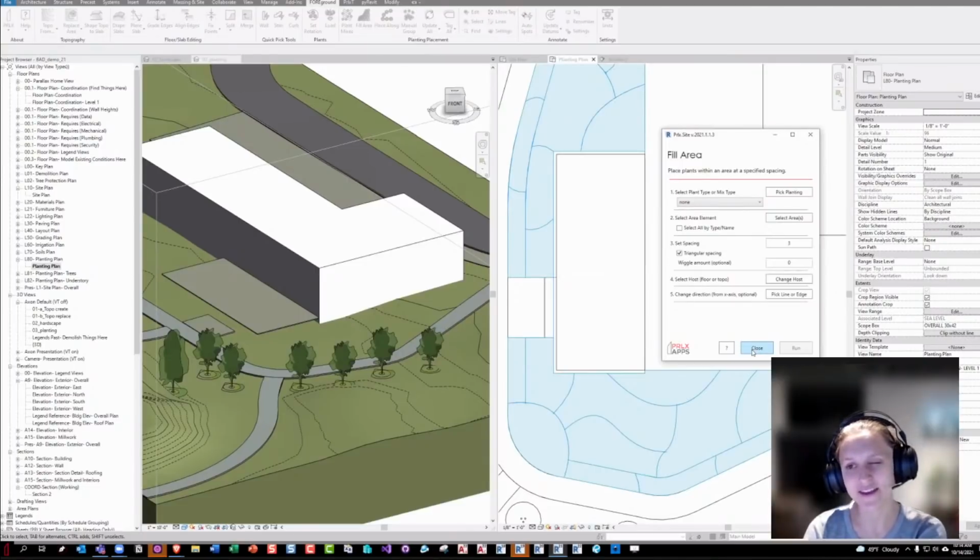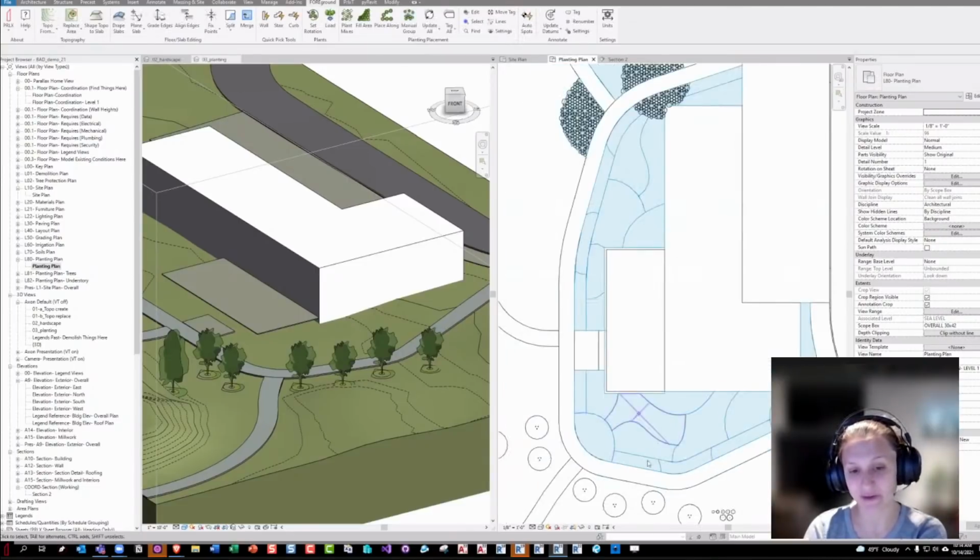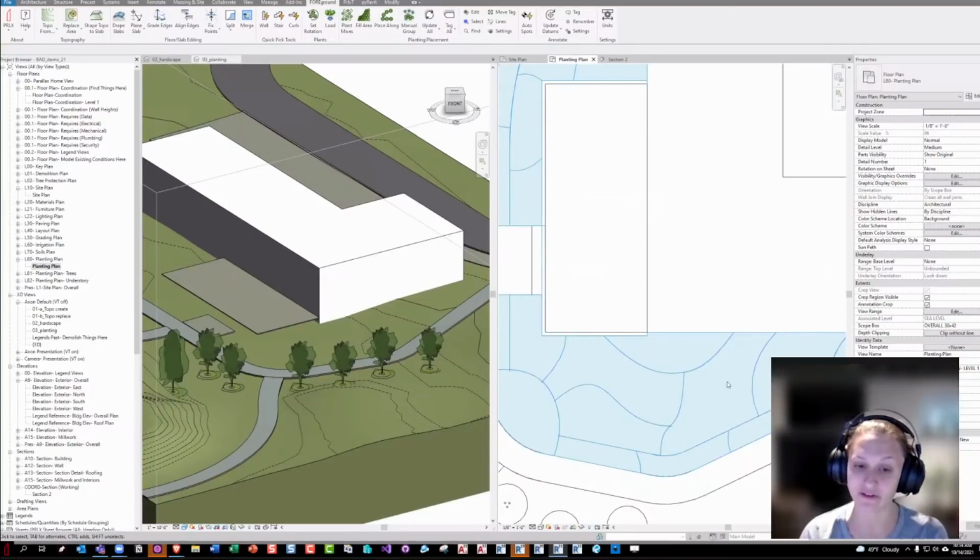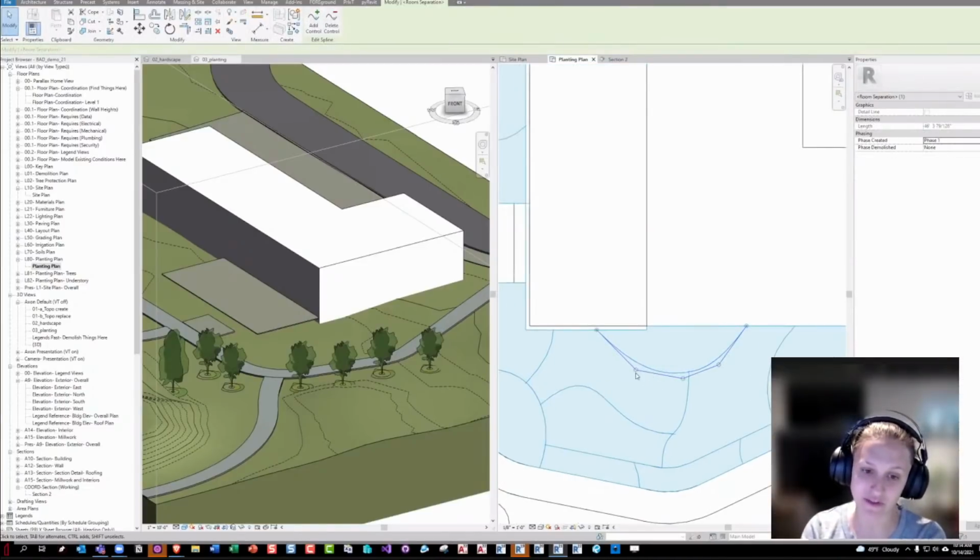Yeah, you could. The thing about floors is, if you're doing a planting plan like this, where you have a lot of shapes sharing boundaries, and these were all different floors, you'd have to go in, edit the boundary, and come back out, and then they'd share boundaries when they change. The nice thing here is you can just drag these around and it updates, affecting both instead of one or the other, and you won't get a "floors share or overlap" error every time you change them.